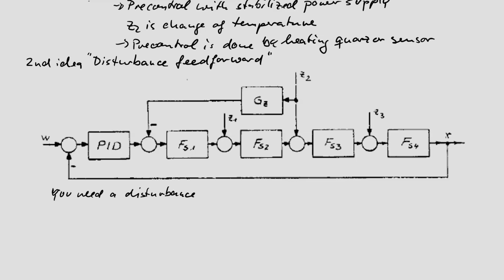If you can afford an additional disturbance sensor, then take the disturbance signal, go through a compensation filter and add this signal directly with a negative sign into your signal coming out of the controller. This is normally a low power voltage signal. This is the actuator. So this is just an addition of two voltages, which costs no money. You use now the still available, already paid actuator.